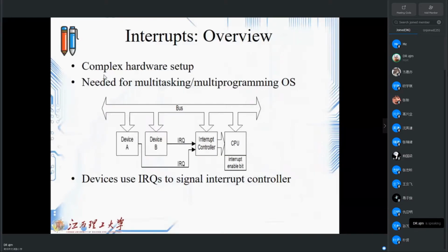Okay. There is a list that they call interrupt priority, and I remember when we studied the 8051, there was a list that showed which interrupt has the highest priority, and you can tune that. The same provision we have for the Arduino board. But as you know, now the crystal for the Arduino is much faster. People will put less effort into changing the priority, but if they want, they can do it on the AVR platform.